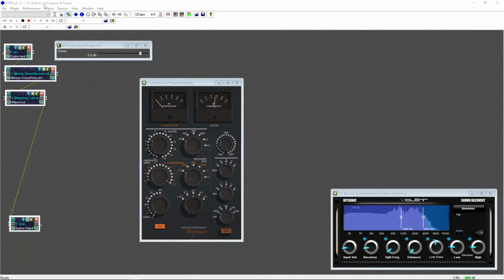That's about an S9 signal, just a little bit in the red. So there's a lot of limiting going on. Now you want the hard limiting on the very strong signals, and what it'll do is it'll allow the weak signals to come through. And what that does is it prevents you from having to ride the gain too much. You know, if you're in a round table and you got someone who's like a 5.7, and then you have somebody who's 10, 15, 20 over, it'll slam the door on that 20 over, preventing you from having to ride it constantly. You know how it practically blows the speakers off the wall.